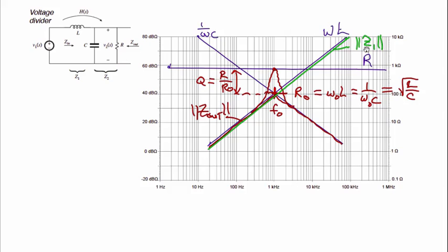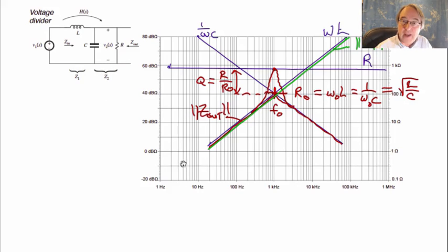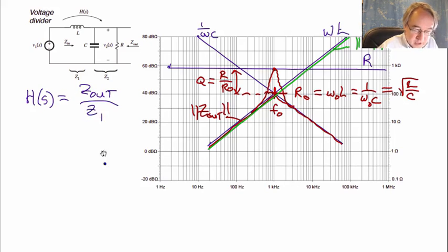And finally we'll construct the ratio. So to divide asymptotes, or to divide impedances, we simply divide the expressions for the asymptotes. So over some given range of frequencies, we express each impedance by its asymptote and divide to find the asymptote of the transfer function. Once again, I'll remind us what H(s) is. It's Z out divided by Z1.